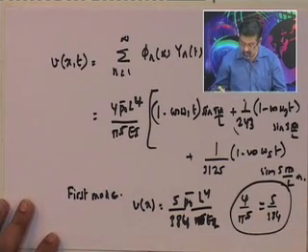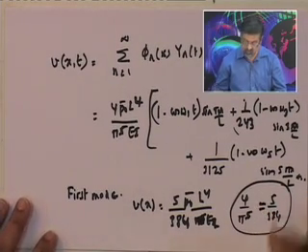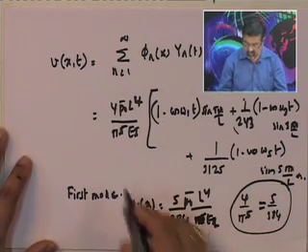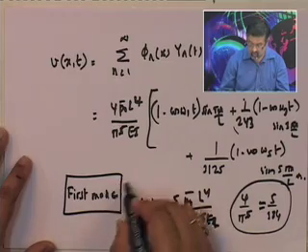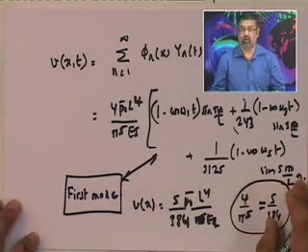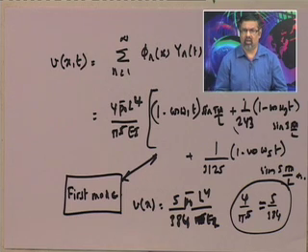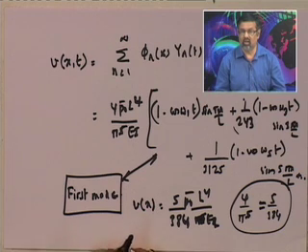So it's very close to each other, and for all practical purposes, we can see that the first mode dominates the response. Remember, even in multi-storied things, I had pointed out that displacement is essentially governed by the first mode.